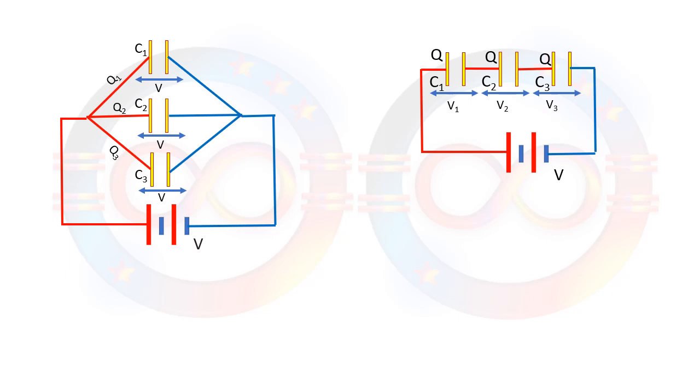So first let us learn the trick we need to apply for any combination, whether it is of resistance or capacitance. Here we are going to emphasize capacitance. The basic formula is Q is equal to CV. If I ask which of these 3 is constant, you will say C is constant. It means if Q is going to change, V will change. There are 2 combinations, parallel and series.